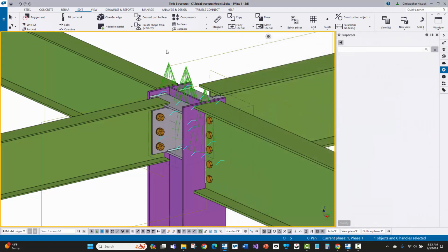So that's interesting. I am not used to seeing that, and I don't think that used to happen in older versions. I'm currently in version 2023, so that is a desired effect here if that's exactly what I want to happen. But usually I used to have 186 applied at column webs and flanges, and then I would just change the settings to load up stiffeners when required and no stiffeners when not required. However, let me explain how this is working and why that's super handy and what it just did.